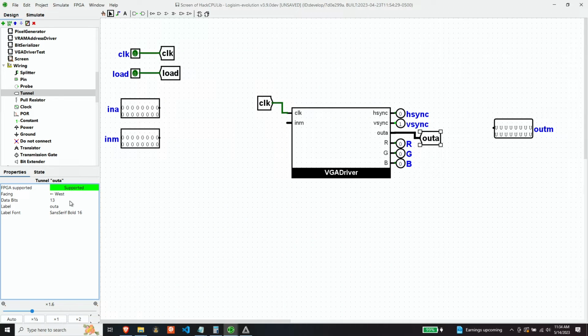How do we arbitrate that access? The way it's normally done in modern days is that you have dual-ported RAM, which means that you have two different addressing schemes where you can address the RAM and get a value back from two different buses, essentially.